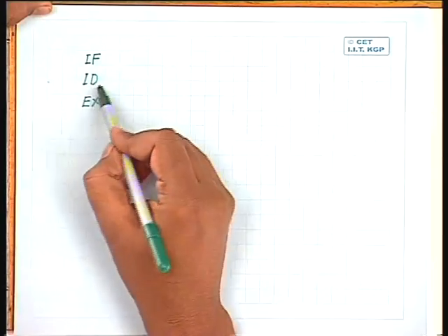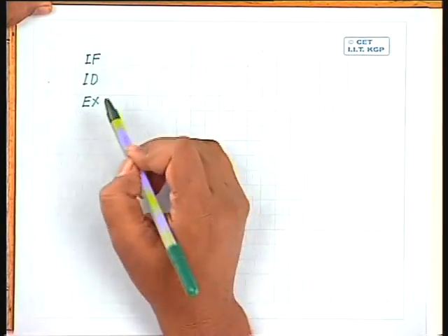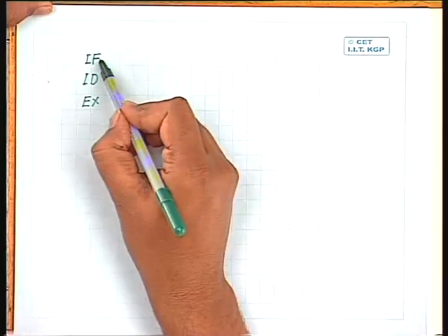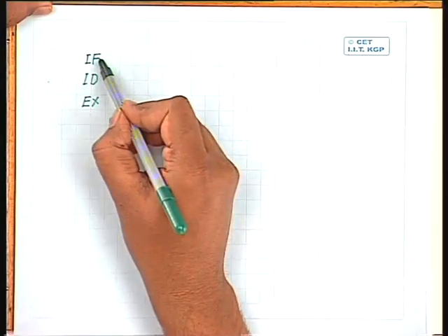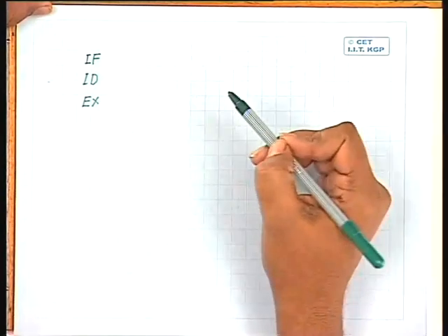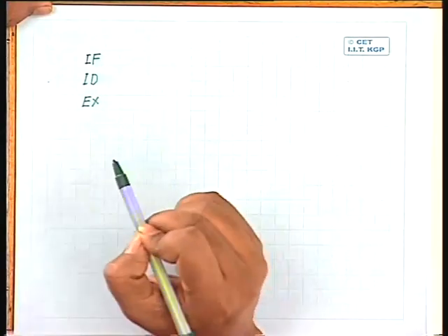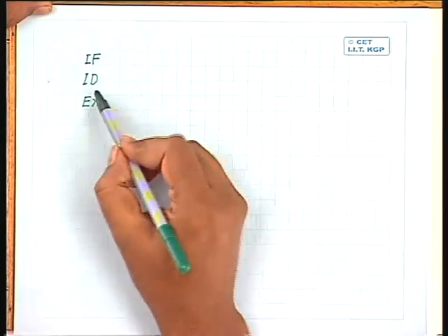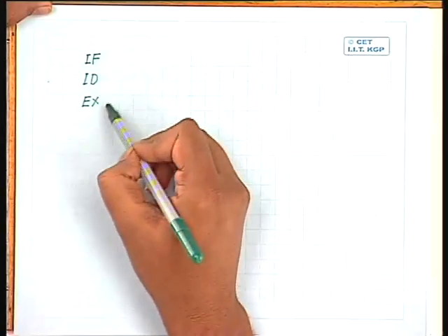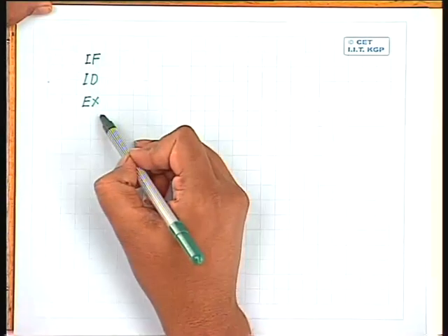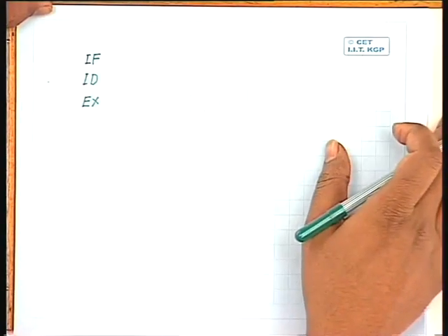So it was thought that why don't you make use of these buses to prefetch some instructions when they are not really needed for execution of the already fetched instruction. That means essentially what we want to have is overlapping of these different stages of different instructions in time, which will lead to a pipelining concept. So that we'll see in the next class.